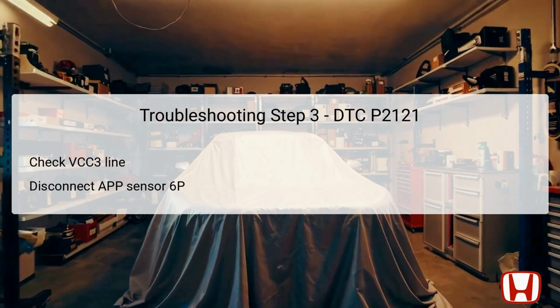Start by turning off the vehicle completely to avoid any accidental short circuits. Disconnect the APP sensor's 6P connector to isolate the sensor from the system. Now, turn the ignition key to the on mode. Measure the voltage between test points, specifically between the female terminals numbered 4 and 5 on the 6P connector. This test will help you check for a steady 5.0 volt signal, which is crucial for the APP sensor's functionality. If you detect around this voltage, proceed to step 4 for the next set of checks.